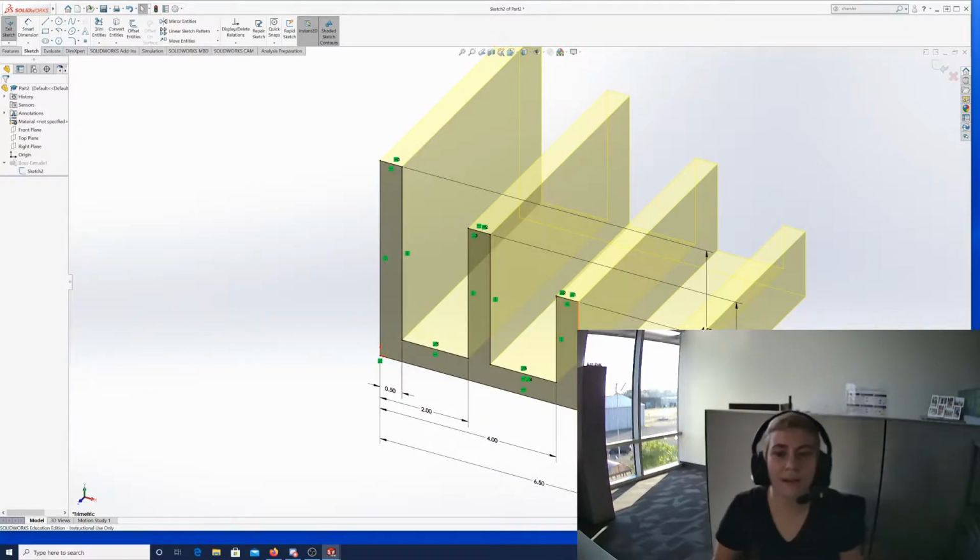So when you add your vertical dimensions, your top to bottom dimensions, it should fix that. It's going to be bigger than what you first sketched, but you can just zoom out. It's all relative to what you're looking at on the screen, so it doesn't really matter. So start adding in those vertical dimensions and see how it looks once you get those. It should become proportionate.